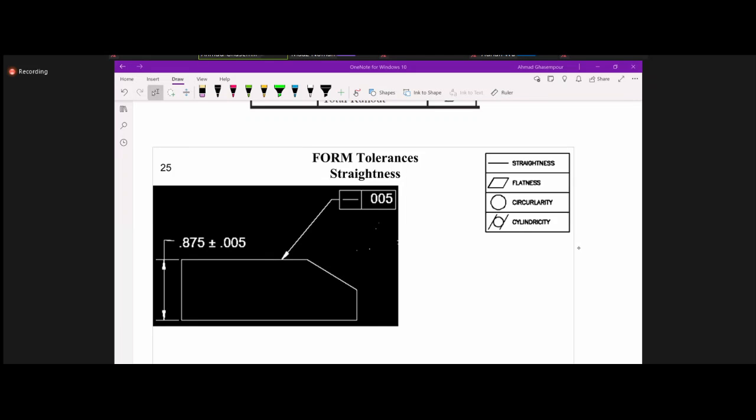So, Jagdishwar, is that what you're going to say? Yeah, I was going to say that you can't really have a datum on it, because a datum is like a reference point. Yeah, exactly, right? A datum means reference to something. But the straightness, like if a line is straight, it doesn't have to be with respect to anything. Yeah, exactly. Exactly because of that reason, there is no datum associated with a straightness, right?